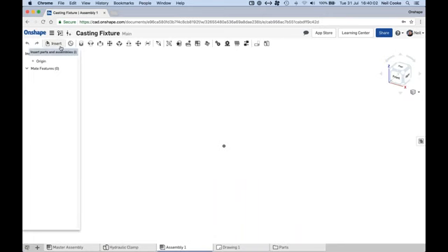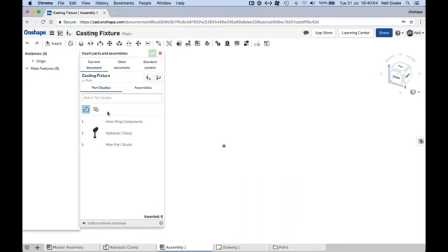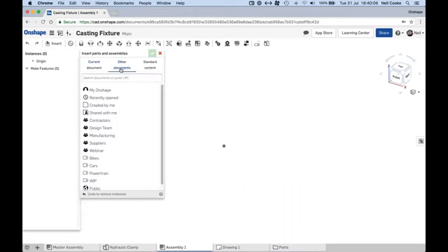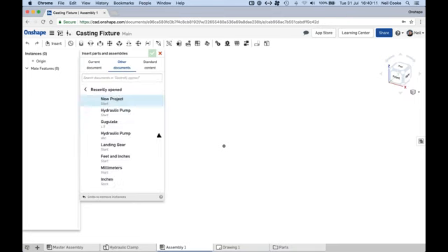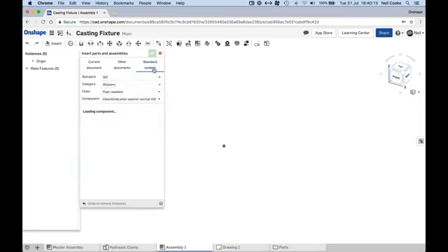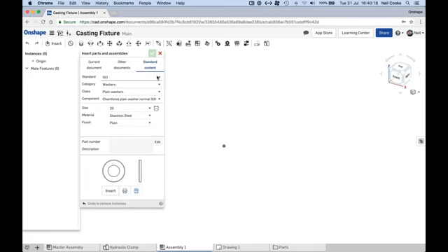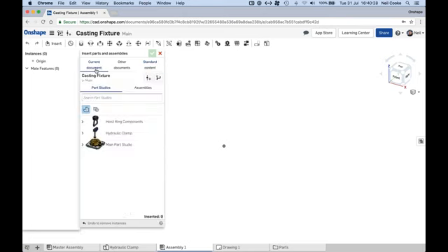And then you can see there's an insert button. So this is going to insert either items from your current document. You can insert items from other documents. Okay, so you've got whatever documents there. There's also a standard content option here. So if you need to do nuts, bolts, screws, and washers, you can insert them from here. So that's included as standard. You don't have to have SolidWorks Toolbox or whatever the Creo equivalent is. You get those capabilities there.